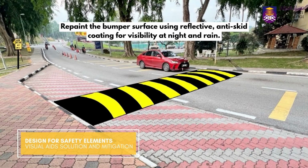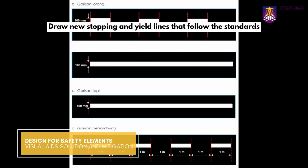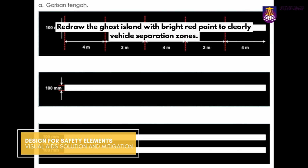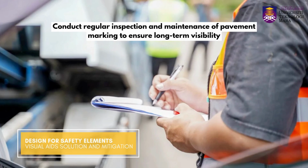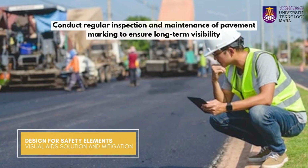Firstly, repaint the bumper surface using reflective anti-skid coating for visibility during night and rain. Next, draw new stopping and yield lines that follow the standard of RIM layout for minor road exits. Next, redraw the ghost island with bright red paint to clearly define vehicle separation zones. Next, conduct regular inspection and maintenance of signage and pavement markings to ensure long-term visibility and compliance with safety standards.